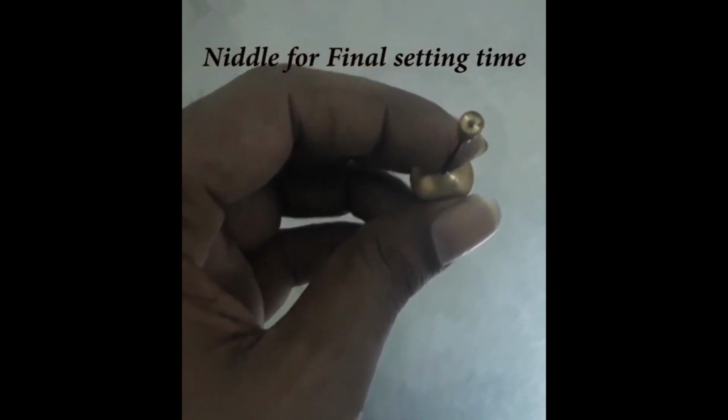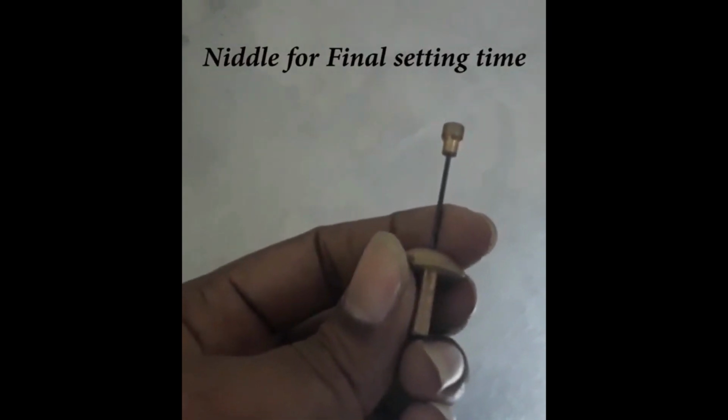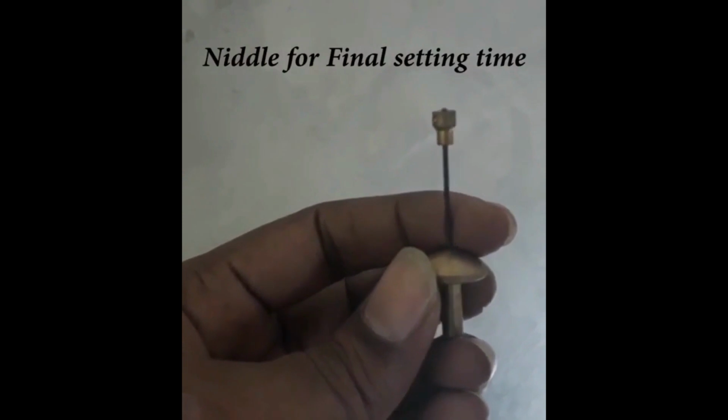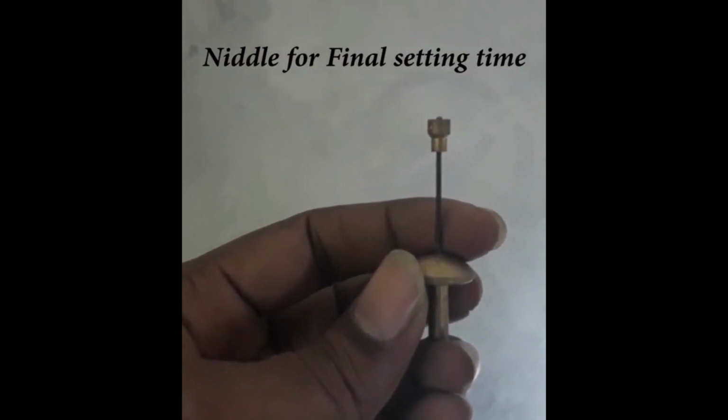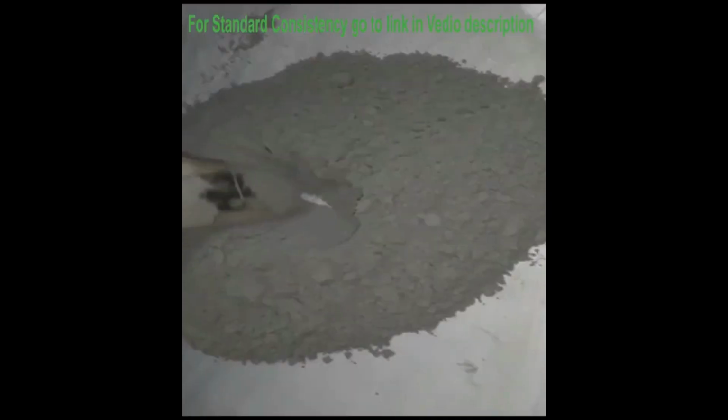Now this is the needle which is required for the initial setting time. This needle is specially designed to carry out the initial setting time test. Its diameter is 1 mm. However, the needle which is shown in the video is required for the final setting time. Its diameter is greater than the needle that is required in the initial setting time.